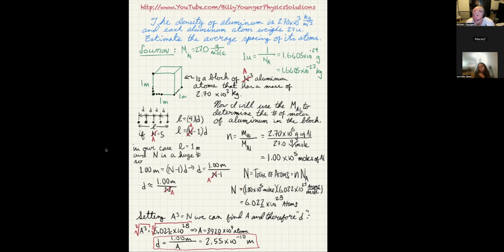You can also use mercury, which is really convenient because mercury has such a high density. It doesn't take very much pressure, or I should say the other way around. It takes quite a bit of change before you can get an appreciable measure because of how dense the mercury is, and therefore you can measure things to a very small gradation.